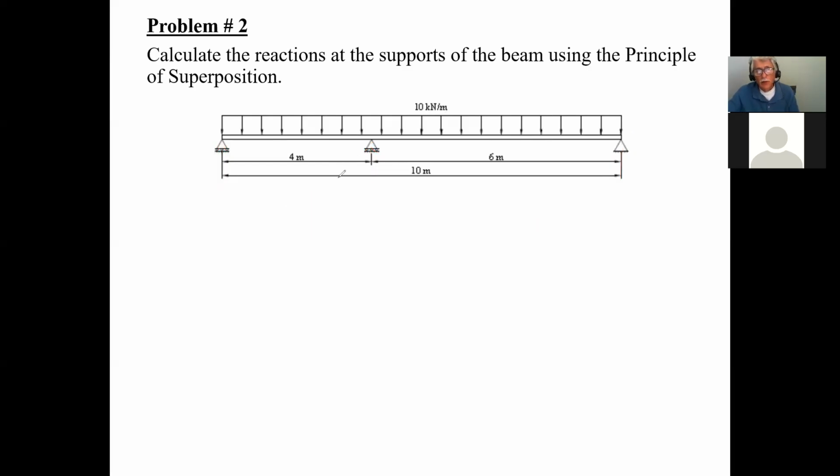So what we do in this case is that we treat this beam and we remove the support here. And by removing the support, we create a simply supported member. And therefore, with simple statics, I can calculate whatever I need to calculate. The concept here is very simple, and when I saw this the first time, I thought this was ingenious, guys. So basically, you say to yourself, let's assume the beam goes from there to there, and we remove that. In other words, we'll take this off.